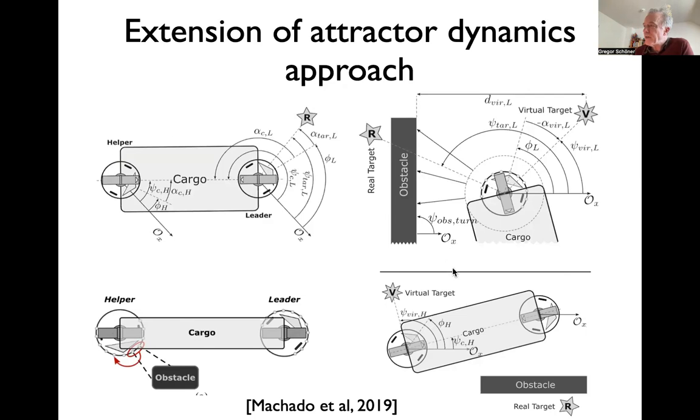And they now have done some special tricks of how to not cut corners, right? You can imagine that would be the problem, that the system might cut corners and then would collide. And actually humans who transport something cooperatively sometimes do run into that problem. And so they have some ingenious way of detecting, under certain configurations, measured by the system comparing the angle to the target and the angles to obstacles, using the distance sensor information, situations where they would be pushed if they were to go too close in our usual way. If this was a robot on its own, it would find the way around here. But that wouldn't be good because the cargo would then collide with the obstacle. And so what they do is they compute a virtual target that adds up these angles in a certain way so as to take a wide turn and head in that direction. And then once it has cleared the obstacle, the computation will abandon this virtual target at some point, and then it would turn to the real target.